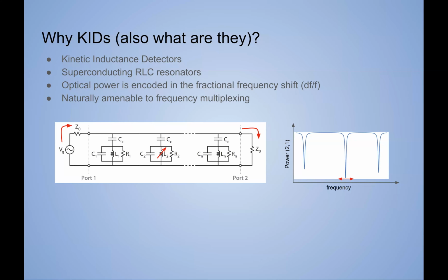And since these are naturally separated in frequency space, it's also just amenable to frequency multiplexing. Basically, what you do is just design each of these capacitors with a slightly different capacitance and hence shift its resonant frequency.